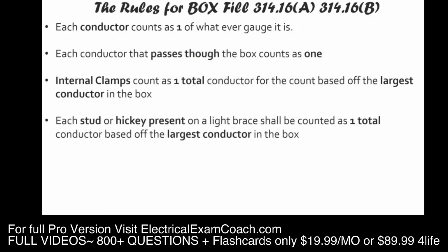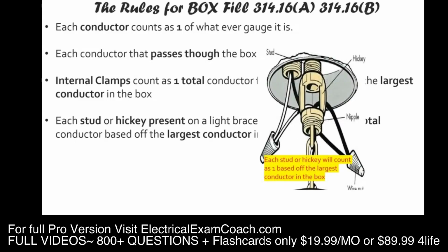Next, each stud or hickey that is present in the box shall count as one total based off the largest conductor that's in the box. Now, these are really old words, probably from the 30s if I had to imagine, but they still use them on examinations today. And this is what we're talking about. Imagine that we're hanging a chandelier. This we would call the stud or the nipple. But they're calling this the stud and this a hickey. And they still use this terminology on exams today, so you definitely need to understand.